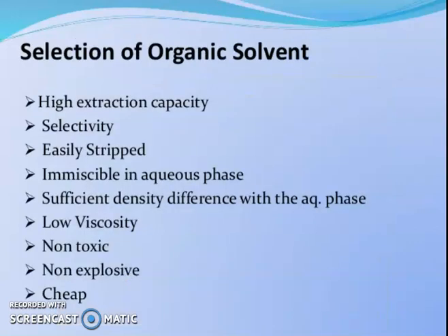Now, selection of organic solvent: highly extractive capacity, selectivity, easily stripped, immiscible in aqueous phase, sufficient density difference with the aqueous phase, low viscosity, non-toxic, non-explosive, and cheap.